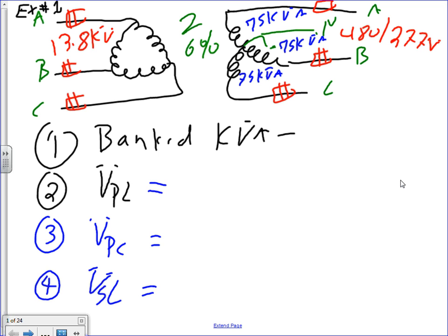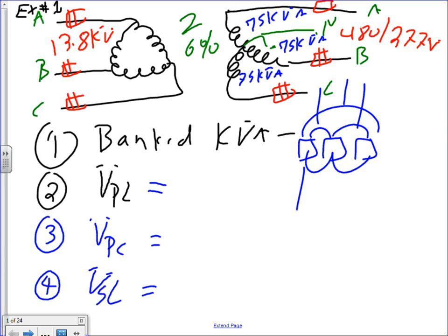All right, so let's use blue here. Okay, so what do we have? We have a transformer connected 3-phase on the primary. On the secondary, guys, instead of having one big fat transformer, they call it a bank of transformers. There are 3 ways of getting a 3-phase system. The best way is to have one big 3-phase transformer. The second way is to have 3 single transformers like these, and they hook them up in delta on one side, and in a Y on the other side.